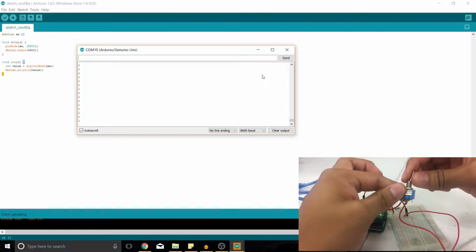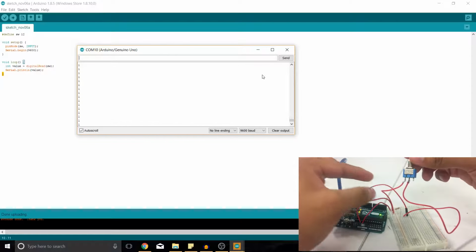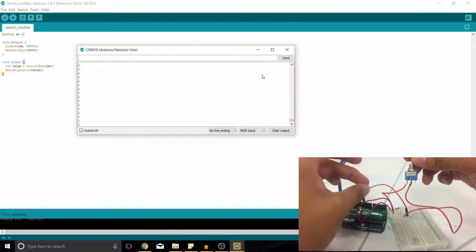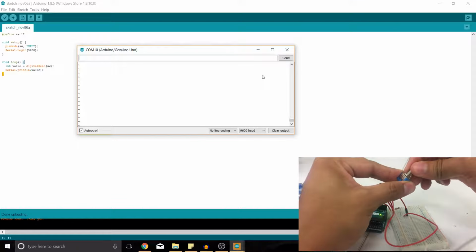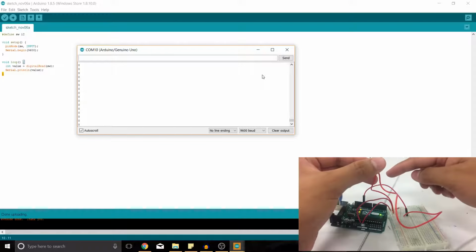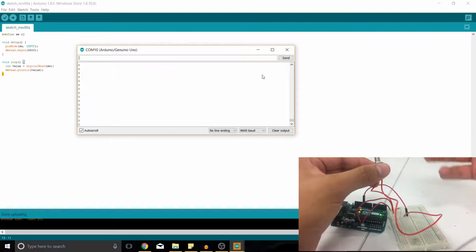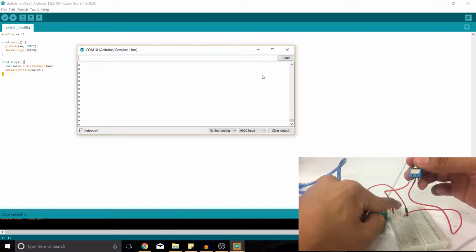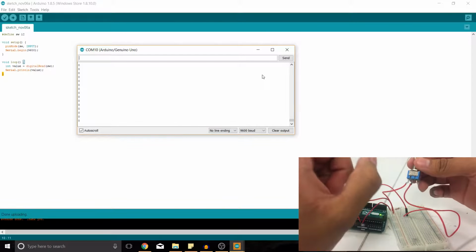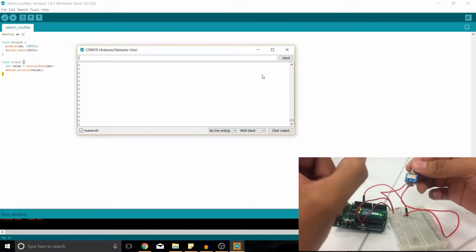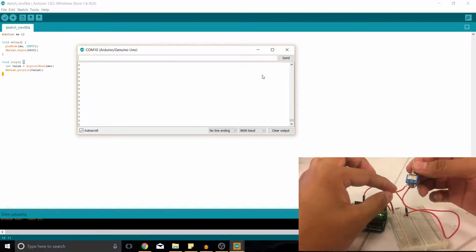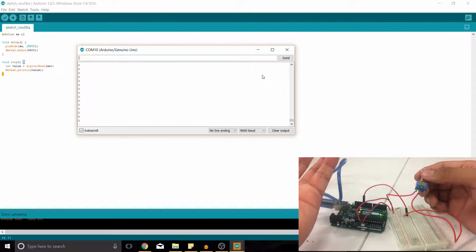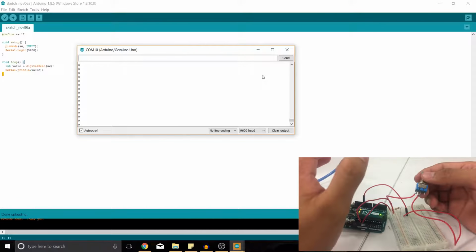That's because if it's connected to positive, then the current is flowing through the switch all the way to the Arduino. But if I don't connect it, now the current is flowing through the resistor, so it's not an open circuit anymore. So the Arduino doesn't have to guess. The resistor is already there telling it that if the switch is not connected, then the default value is going to be 0. Okay, so now we can read 1 and 0, and that may be useful.